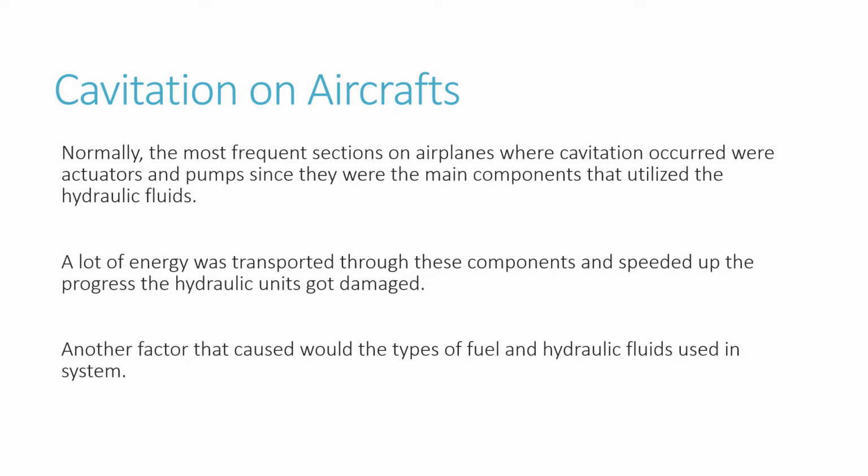Another factor would be the types of fuel and hydraulic fluids used in the system. It is intuitive to think that different fluids would have different properties and performance under certain temperatures and pressures, which can significantly affect the extent of cavitation.